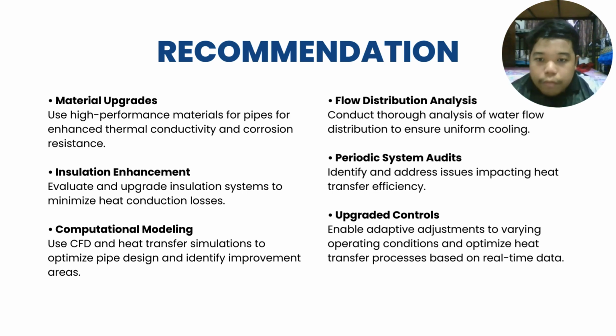Next, computational modeling. Use CFD and heat transfer simulation to optimize pipe design and identify improvement areas. Next, flow distribution analysis. Conduct thorough analysis of water distribution to ensure uniform cooling. And next, periodic system audit. Identify and address issues impacting heat transfer efficiency. And lastly, upgrade controls. Enable adaptive adjustment to varying operating conditions and optimize the heat transfer process based on real data.